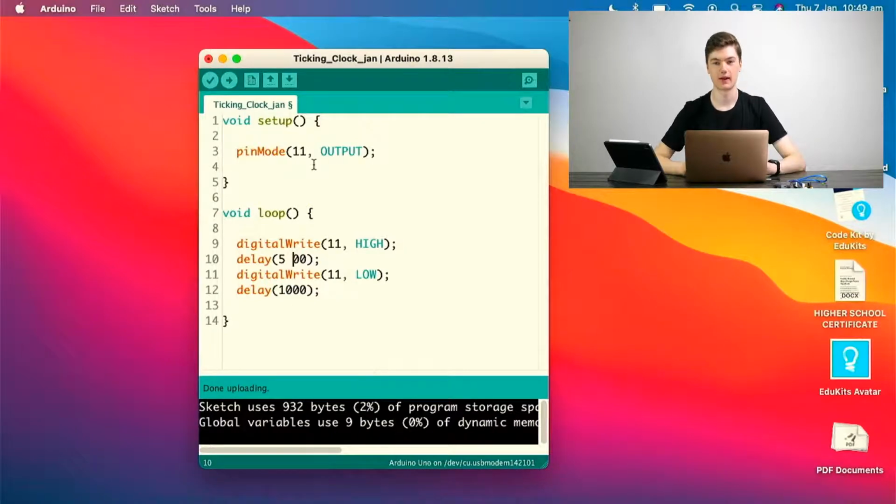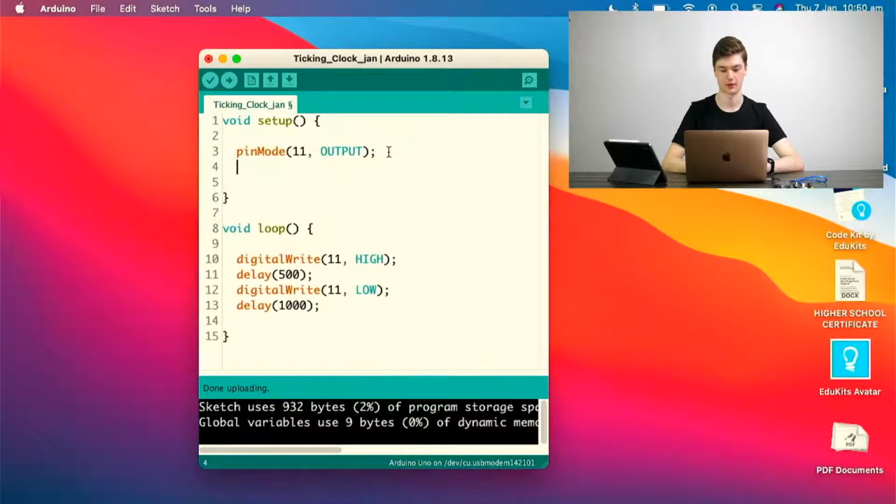So, now that we're back on our computer screens, you should be able to see my code. We are setting the buzzer as an output, then we're turning it on and then off again after a delay. Now, to begin with the LED, we have to first set it as an output. So I'm going to hit enter to create a new line, and I'm going to type pinMode. The M has a capital, and you'll also notice that you've typed it correctly when it lights up orange. I'm going to type 6 because that's where I connected the positive leg to, and I'm going to type OUTPUT